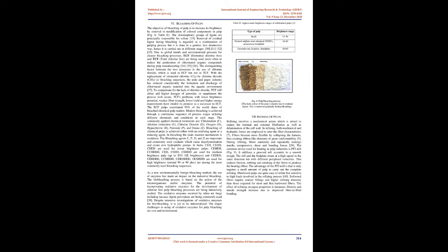The 3 main mechanical processes commonly used are stone groundwood (SGW), refiner mechanical pulping (RMP), and thermomechanical pulping (TMP). The SGW pulping process involves taking a log and pressing it against a rotating surface to grind off small pieces, Fig. 7. The groundwood pulp is then often cooked to soften it. This pulp is used in newsprint and other low-cost book grades where it contributes bulk, opacity, and compressibility.